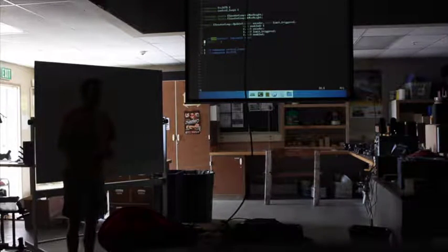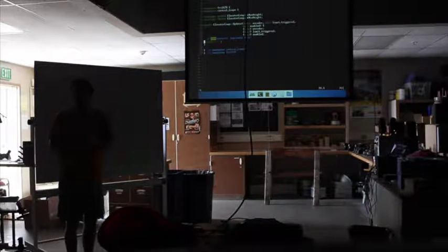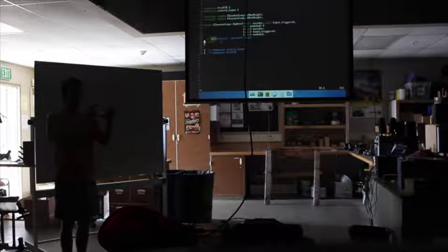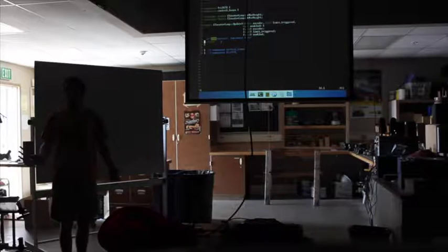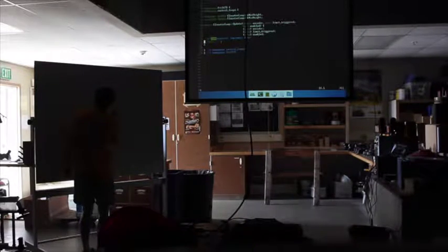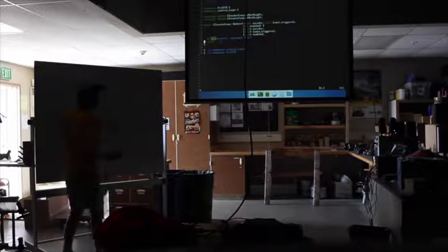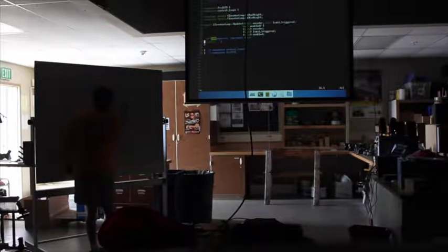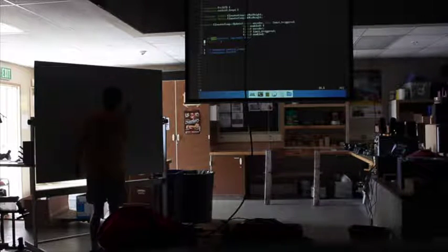The way I like to structure the software for something like this is we're going to have a piece of the code whose job is to figure out where to go, and then a piece of the code whose job it is to go there. So you'll have, say, some goal coming in. This will go into our zeroing box. And this will go to a PID loop.